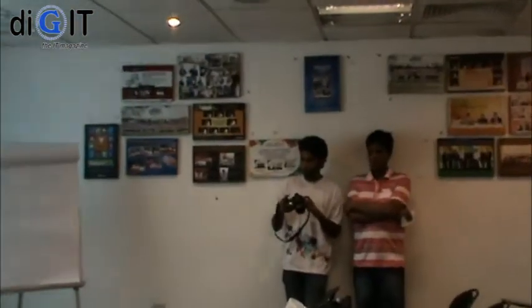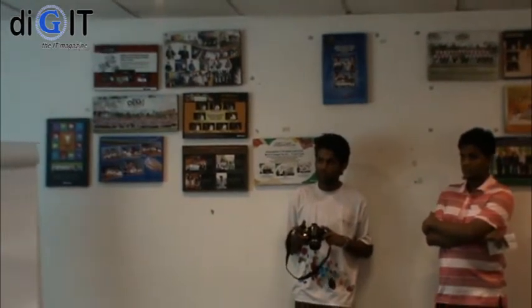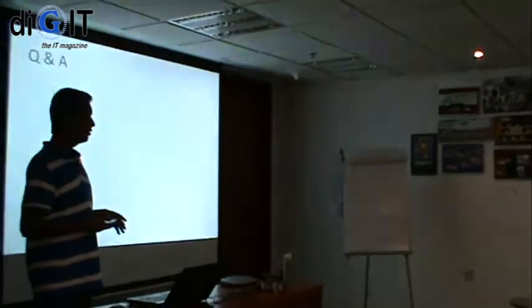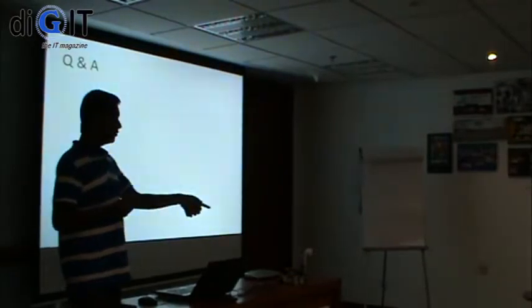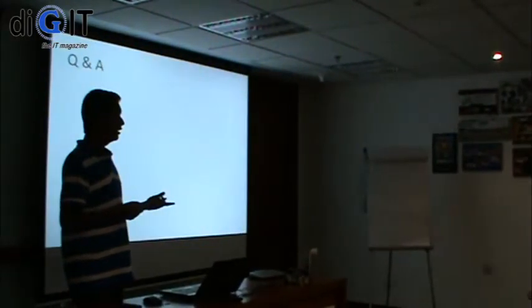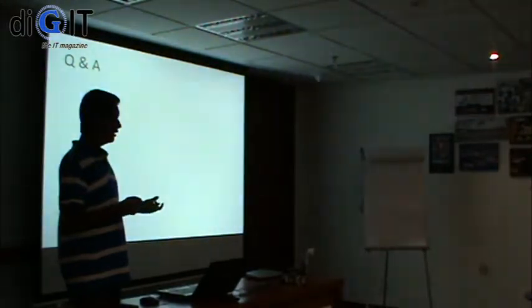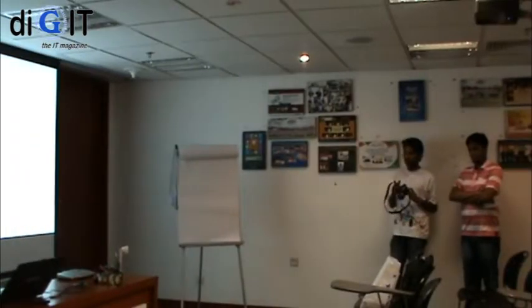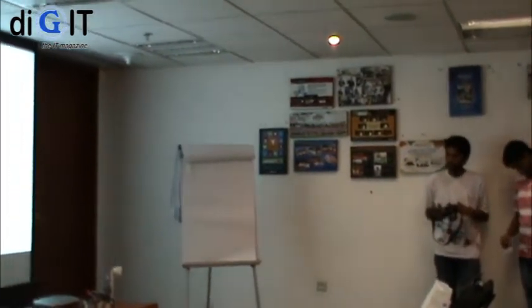So you have to connect Wi-Fi separately to this robot, as the BeagleBone doesn't support Wi-Fi. I think some people have told me that BeagleBone also supports Wi-Fi using a USB Wi-Fi module. But here I am using a mobile phone to connect to the Wi-Fi. You can use a mobile phone with USB tethering in Android phones. You can connect an Android mobile phone and have a Wi-Fi connection. You can also connect an Ethernet cable and connect directly to the internet.